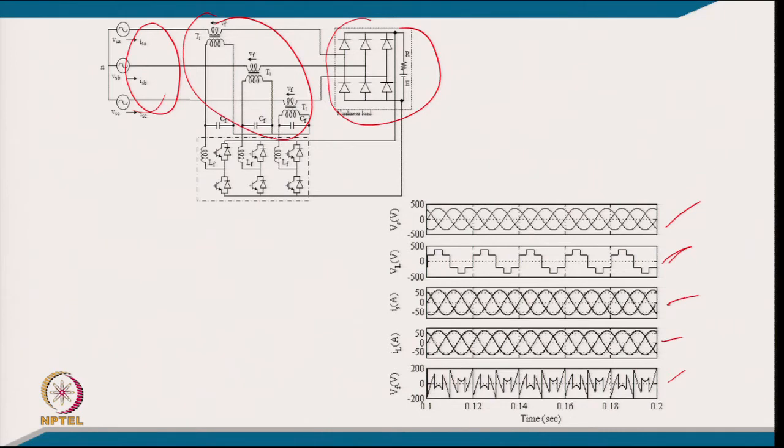through diode and charge the battery. This also gives a very interesting result in the sense that you do not have any ripple voltage on the DC link, as far as the diode rectifier is concerned, because we will be charging from 3 sinusoidal currents, and the sum of the 3 currents at any moment of time is virtually 0. So, that is about the simulated waveform.